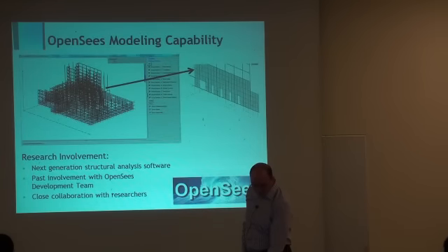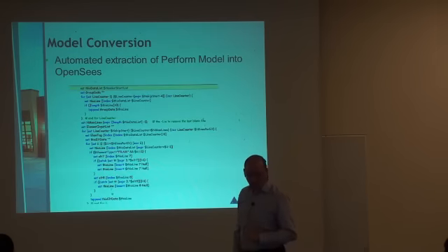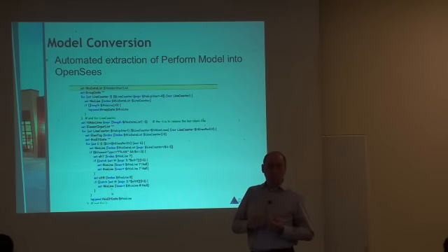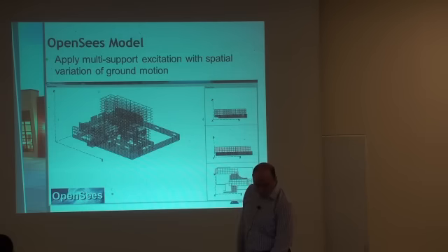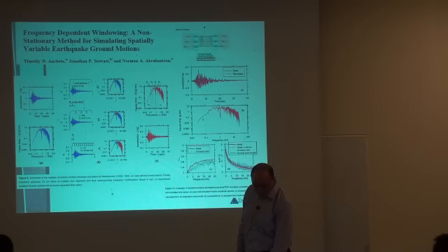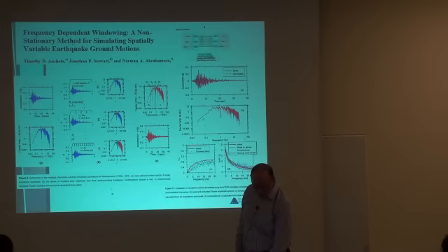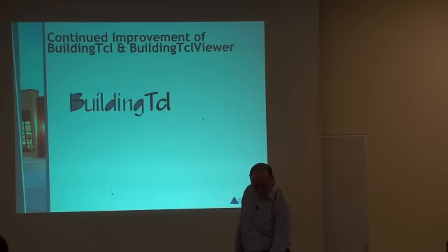So again, this is a model that we use to convert from Perform to OpenSees. We had to write some scripts that would take input files from Perform, convert it to OpenSees. Not a trivial problem because the input is very different. But that again goes into our set of, hopefully will go into our set of tools to do that. We've been using some multi-support excitation in OpenSees.